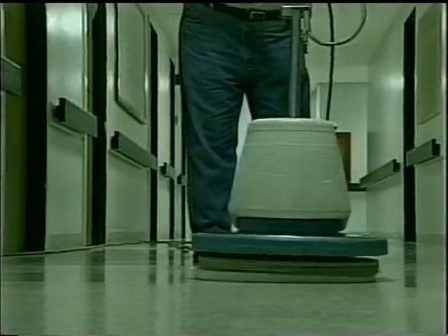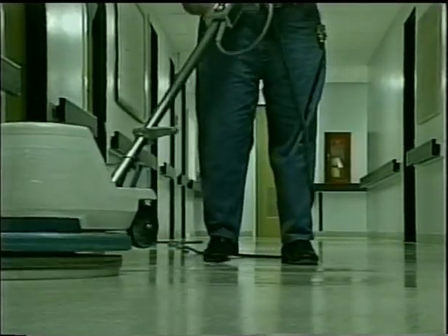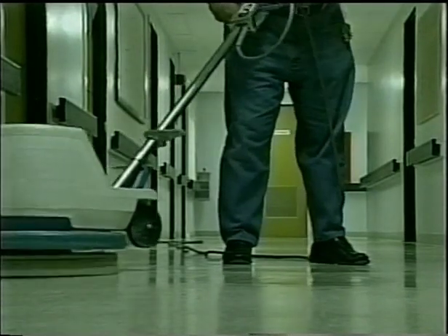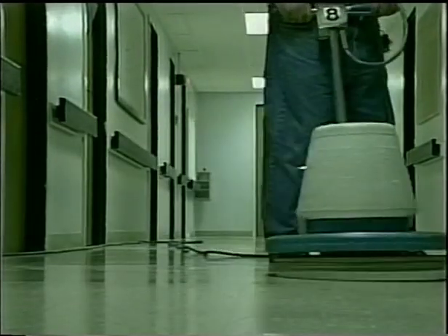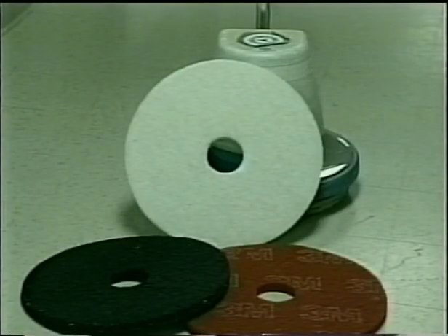Housekeeping and custodial care. Housekeepers and custodians should never sand or dry buff asbestos-containing floor tiles, and only wet stripping methods may be used during stripping operations. Low abrasion pads should be used at speeds below 300 RPM. Broken or fallen ceiling tiles should be left in place until identified. Only after they've been identified as safe may they be removed. Asbestos tiles will be removed by asbestos abatement workers.